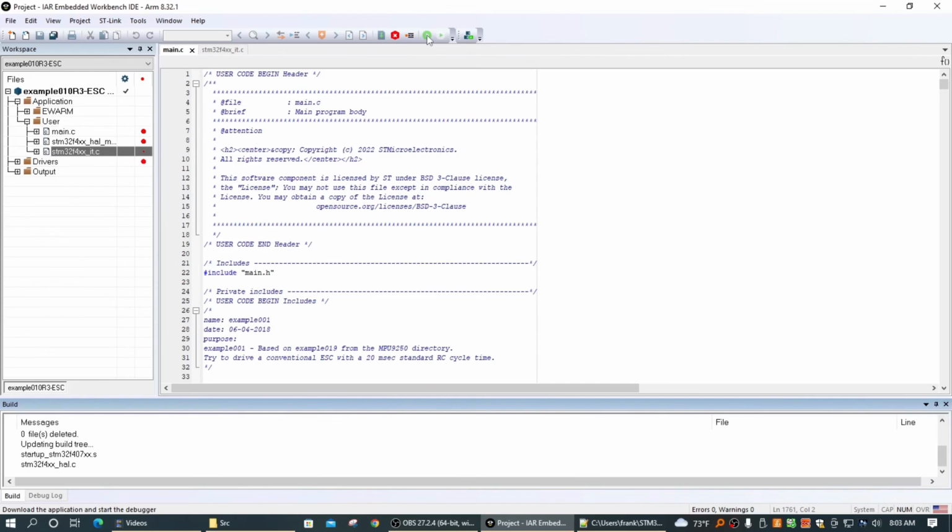So it's going to recompile everything, put all that code. The CubeMX made that template, and then the user code goes into main.c, and I have a little bit in the interrupt, so that services the interrupt, so when the timer runs out, it restarts the frame. So that's what sets the 500 hertz update rate.